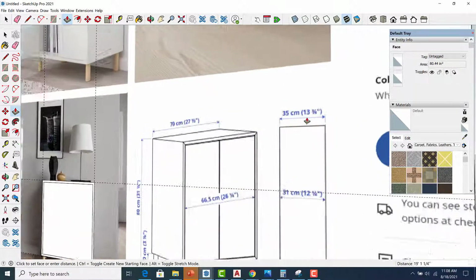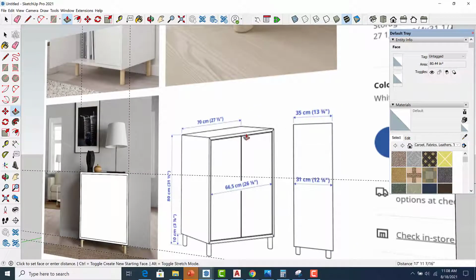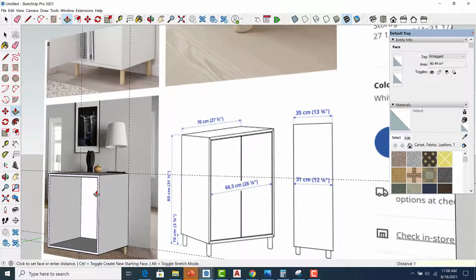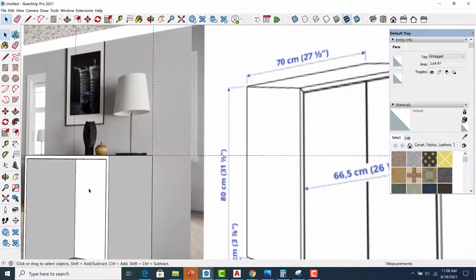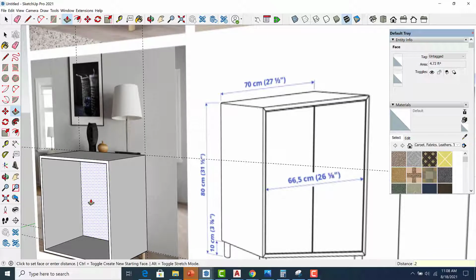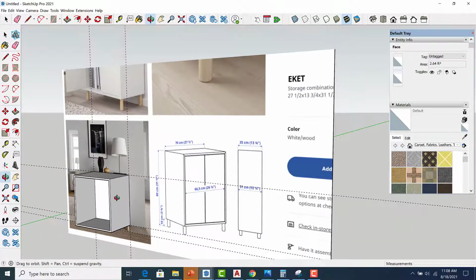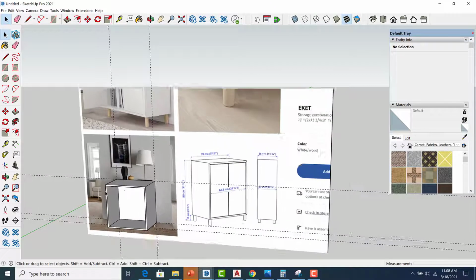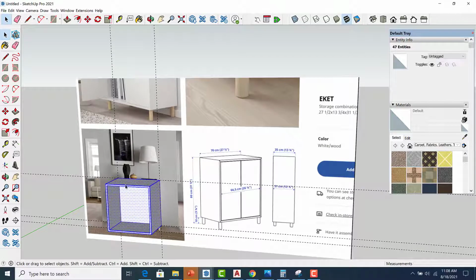see, it's 13 3/4, so I pull it 13.75. For the backing I want to give it a little bit of thickness. Again with the push-pull tool, anything like 0.25 would be fine. Now I have my box, it's one object. I triple click, right click, make a group.